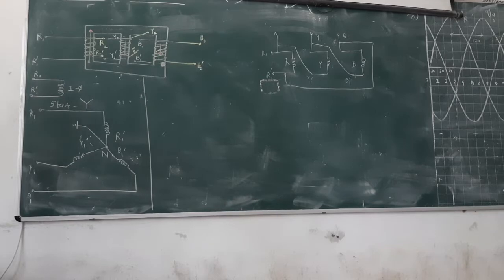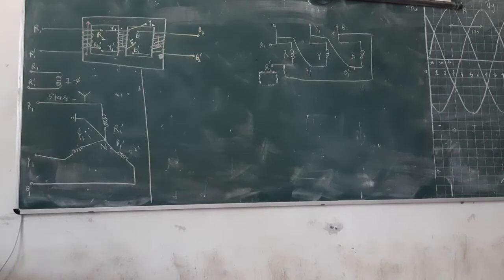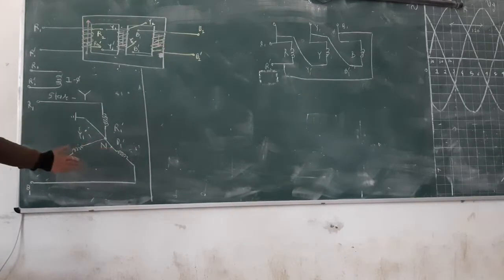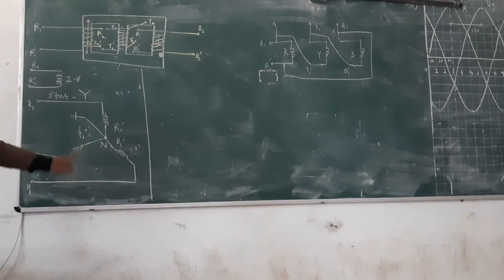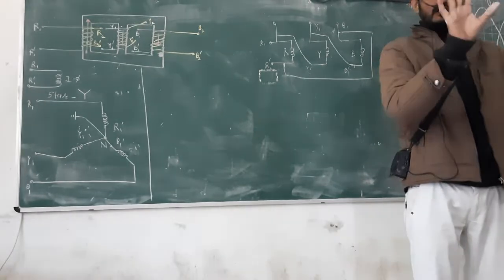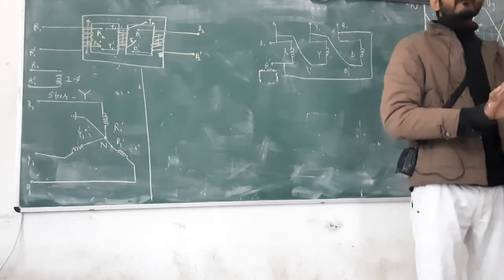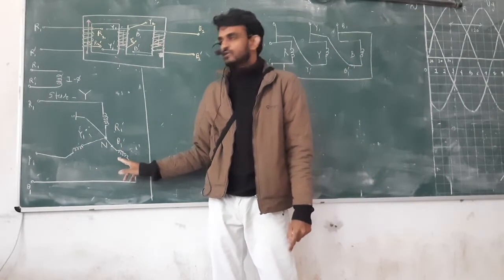And what is the meaning of balanced load? All the windings have the same impedance, or we can say resistance. If 100 ohm is there, then 100 ohm and 100 ohm should be there. R and L are there: whatever the magnitude of resistance and inductance, the same should be in this winding and in this winding. Then we can say that the load is balanced. So what does it mean that the 3-phase supply is balanced? The voltages should reach the perfect value and have perfect phase balance. What is a 3-phase balanced load? It means all the ohmic load impedances should be the same.